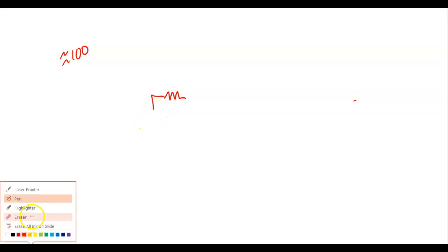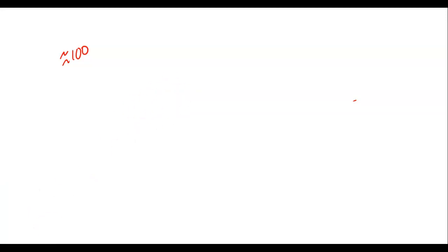And we'll see how my calculations work. So typically for the 3904, we can use a beta of around 100 just to start off with. And beta has no units, right? You understand, because it's a multiplier or divider. So over here, I've got a 5 volt supply. So let me show you the actual circuit.